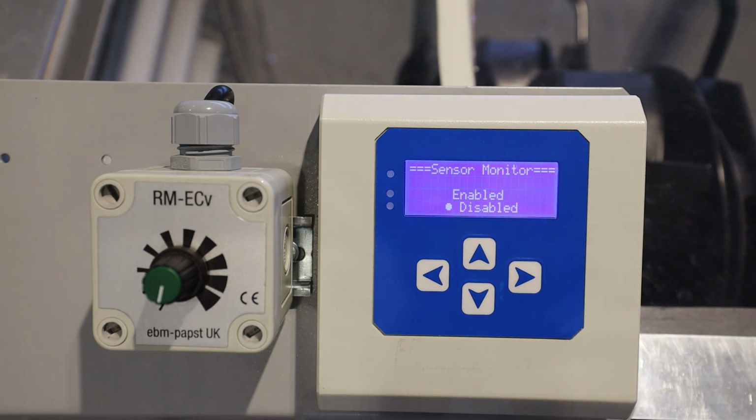At this point, if a pressure transducer has been installed at the control input of one of the fans in the array, or the control input of the MDC controller, the option Enabled should be chosen. If the pressure sensor option is chosen, the MDC will request input on a number of choices. Firstly, whether the output of the pressure transducer is installed at the fan analog input or brought out to the control input on the MDC controller.